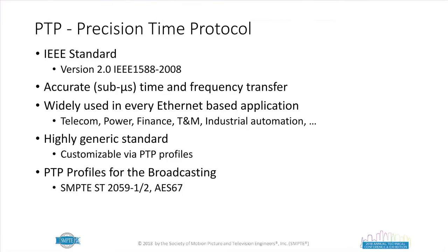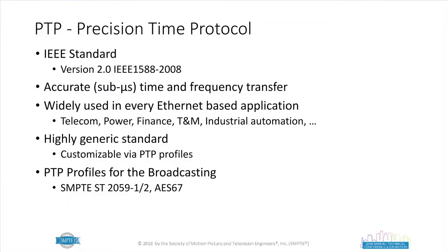We can reach sub-microsecond precision. By the way, we can actually reach sub-nanosecond precision in very well-engineered networks. I was actually attending the ISPCS, which is the main IEEE 1588 conference a few weeks ago. And if you want a projection in the future where PTP actually needs to go, they're talking about tens of picoseconds. Okay, completely different scale in terms of time and accuracy they need. So we are not the ones who have the strictest timing requirements in the industry.